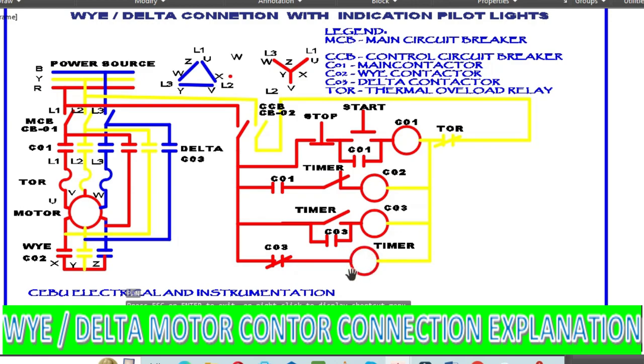See, when you switch on this one, then there is an interlock normally closed from CO3, then your timer is already energized, already counting. Once this timer is counting the setting time, this timer normally closed contact will be open. Once the time setting of the timer is over, this contact normally open and this contact normally close will change to close and then to open.